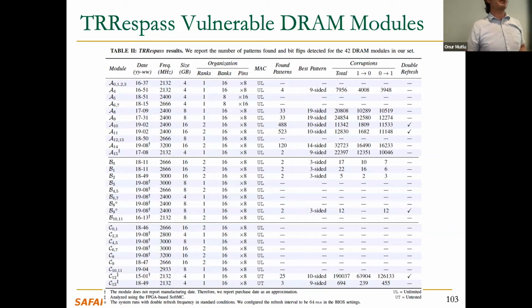We were able to induce bitflips in 99% of the bits, after you bypass all of these mitigations. This is not the latest work. Roughly, with whatever reasonable refresh and stuff like that. I don't know the exact percentage, it depends on the manufacturer, but I believe 99% of the rows you can induce. I don't know the exact bit count.